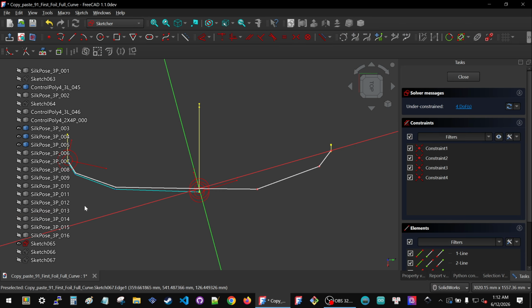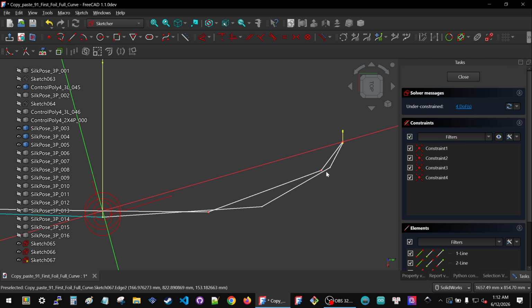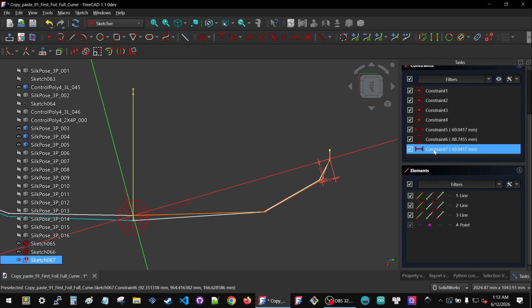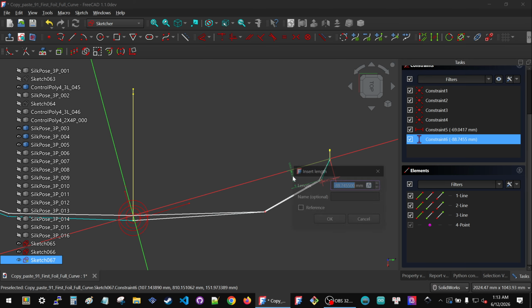Get myself in top view. Turn that previous sketch back on so I can see kind of what I did. Drag things so that the top rail looks a lot like the bottom rail. And now I select this point and then this point, KL. It creates doubles, but I don't care. I just delete the extras. This is worth it for me. This is going to be a stable sketch that's dimensioned just like the other ones at the other end.